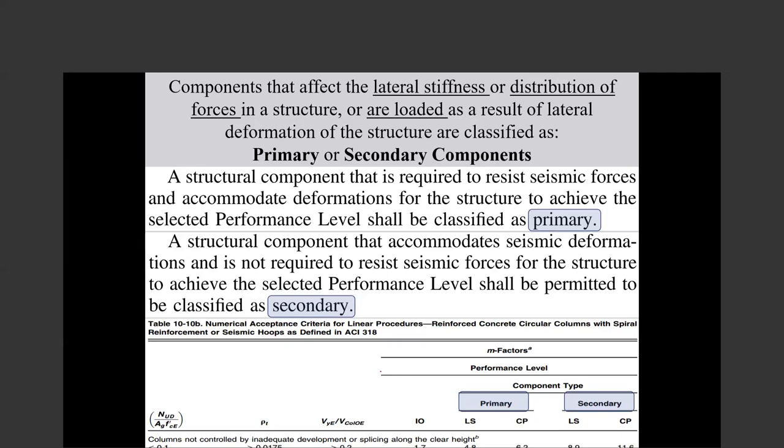There is no time, but we have the same concept for new buildings too. When you design the building, most codes let you assume that all the frames in one direction are moment resisting frames, concrete moment resisting frames. But you as a designer can assume just these two at the perimeter are the lateral load resisting system, and the middle ones, for example, are secondary, gravity only.